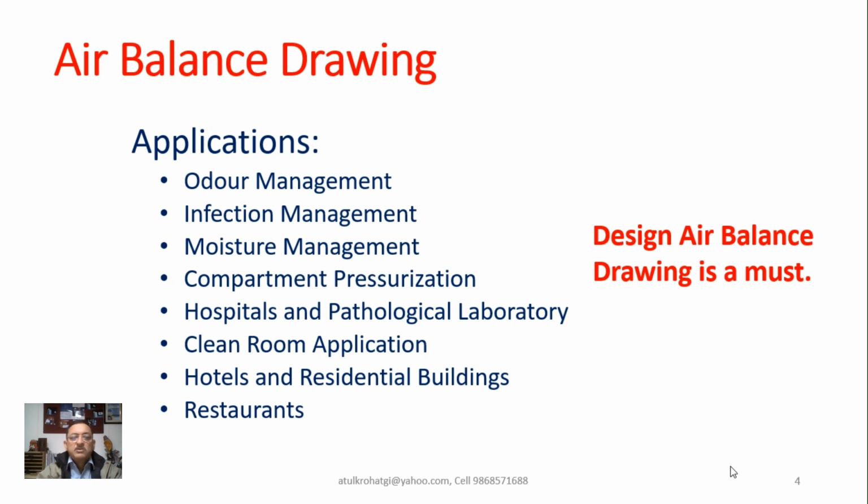The applications of air balance drawing are odor management, that is smell management, infection management, moisture management, and compartment pressurization, which cannot be done without doing the air balance drawing. These include hospital and pathological laboratories where infection control is essential, and clean room applications where dust control is essential. There are many compartments that need to be positively pressurized and there are compartments that need to be negatively pressurized.